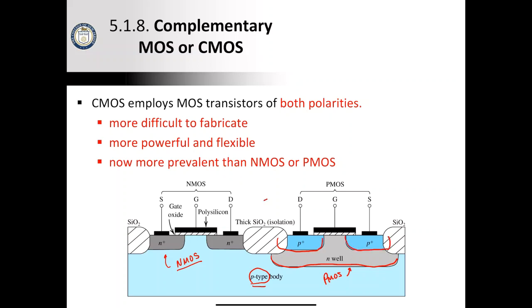You also need to have a very thick dielectric material to isolate the transistors from one another. So you can see there are some more difficulties associated with making this kind of hardware as compared to just doing regular old PMOS or regular old NMOS.